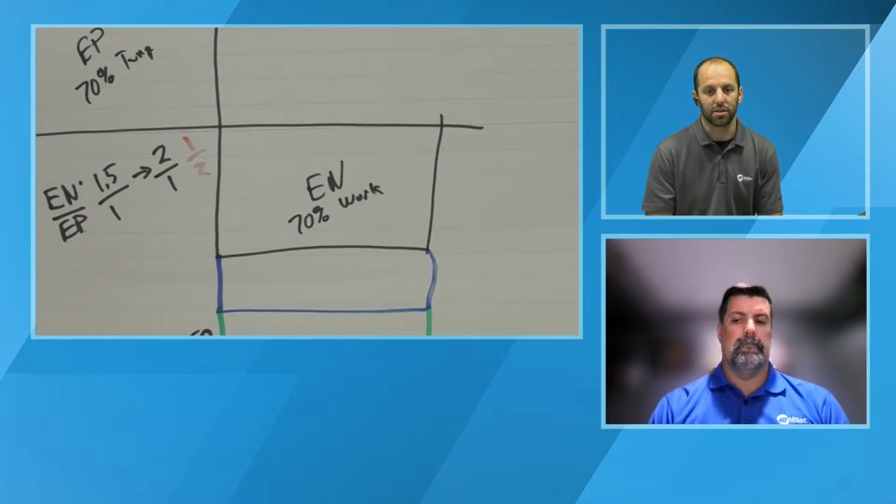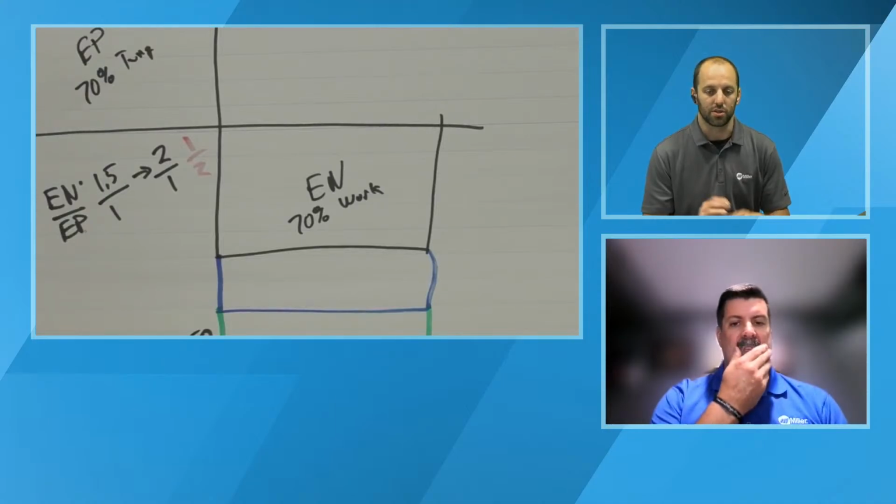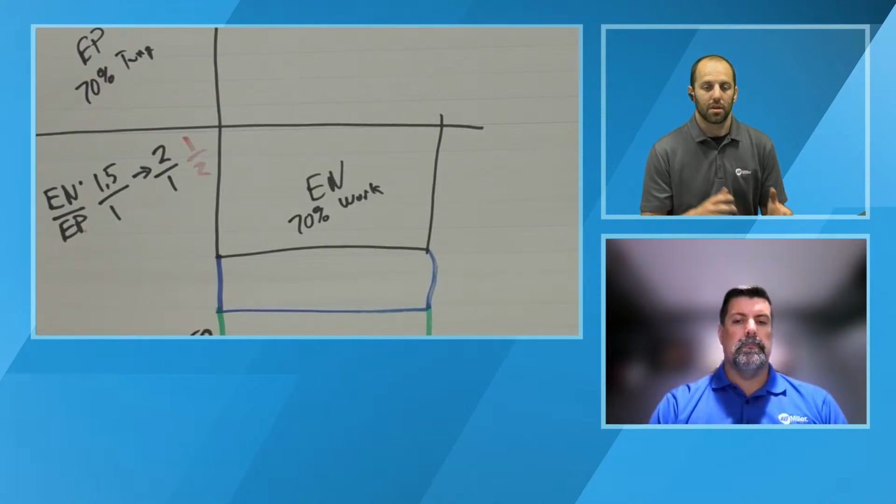So it's not necessarily a disadvantage, and in some cases you may want to, but for most applications, people are typically choosing a TIG welding process because it's thin materials, it's very delicate, and they're trying to get a small weld. That's why, for the most part, we generally recommend using that truncated tungsten geometry. In many cases, if they're trying to do a thick section, they might have the opportunity to MIG weld it. In some cases they might not, but they might be choosing an alternative welding process if it's that thick or large of a section.